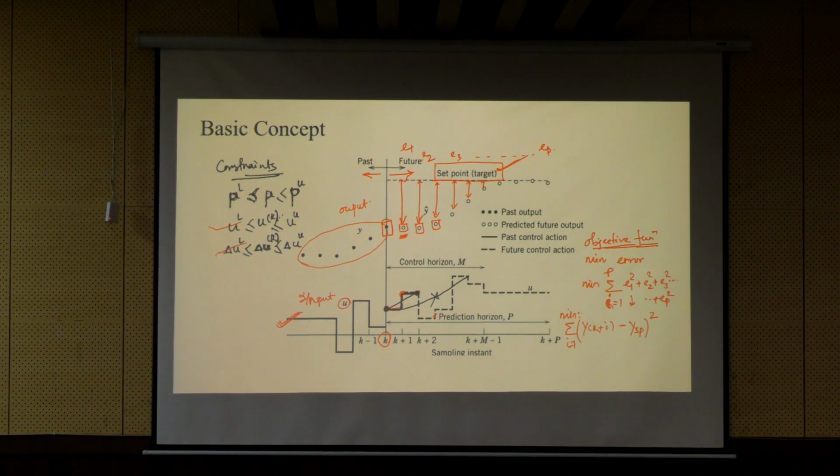The del u is nothing but the step change in the manipulated variable. We can assign a weight to it: whichever gives a more closer response towards the set point, we will give more weightage to it, and we should ensure that the sum of all the weightage equals 1. So that is how the MPC works.